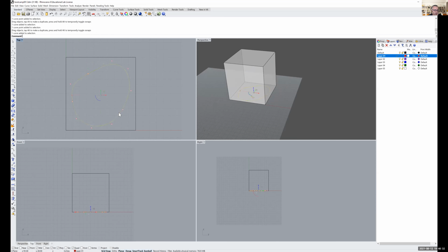And so what I want to do is just click on that shape, and in the front view or side view, let's move that up, let's say 7 inches. And so I just did that by moving. M for me is move, where when you type M, you see all of them come up.